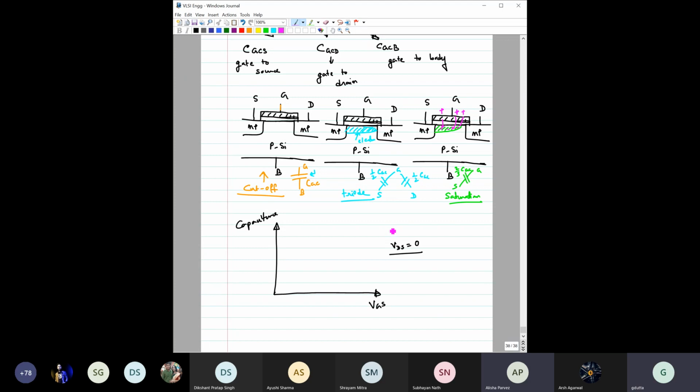If you have understood this thing, and let us also see whether you have understood or not, then you will also be able to guide me in this case. Say we want to plot the entire capacitance, this gate to channel capacitance, versus this VGS, when VDS equals 0. Remember VDS equals 0, source is already 0, so you are now also grounding the drain terminal.